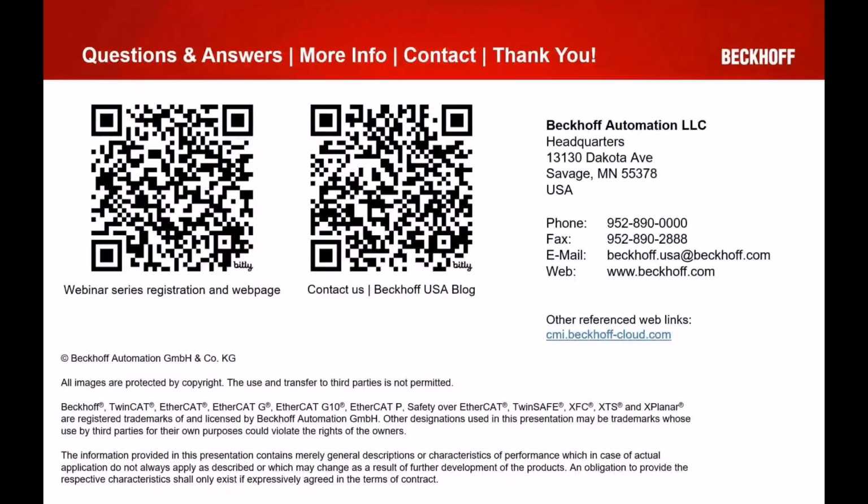All right, some other questions that I get a lot around this product. One, is TwinCAT HMI only for Beckhoff PLCs? That's a really good question. The answer is no. One of the extensions that you can add to your TwinCAT HMI project, another server extension, is an OPC UA client. So then you can communicate. You have all the same features dealing with symbols, binding them to controls, but it's with an OPC UA device instead of with ADS with our TwinCAT PLCs.